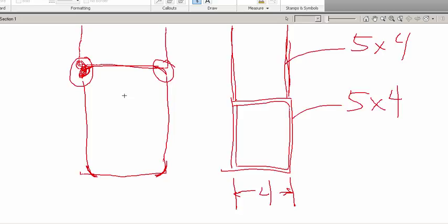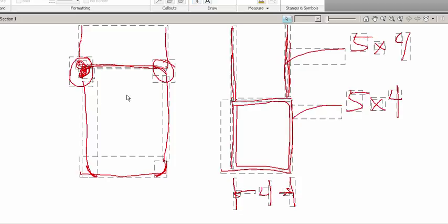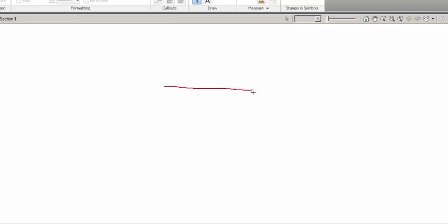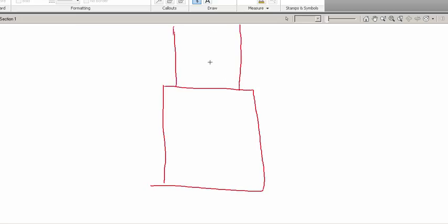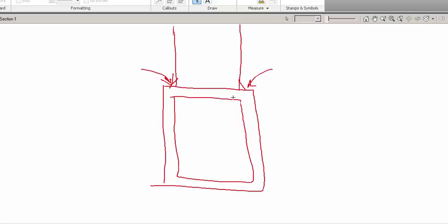If you're looking at a set of plans that brings the same size tube perpendicularly into another piece, and you're going to do a fillet weld all the way around, be aware that it is actually better, especially if you end up doing a little sketching or doodling to make some recommendations, to size one bigger than the other. So for example, let's say that we do a 5x5 against a 5x4, so that we have that 1/2 inch there and there to work with. Much better result. I learned that from some of my guys not too long ago in specification and it worked well on a project. It just helps them out. Whenever on the design side we can help folks fabricate better, that's what we're after. And when you're reviewing a set of plans and they have things like that on there, it never hurts to make some suggestions and point that out.